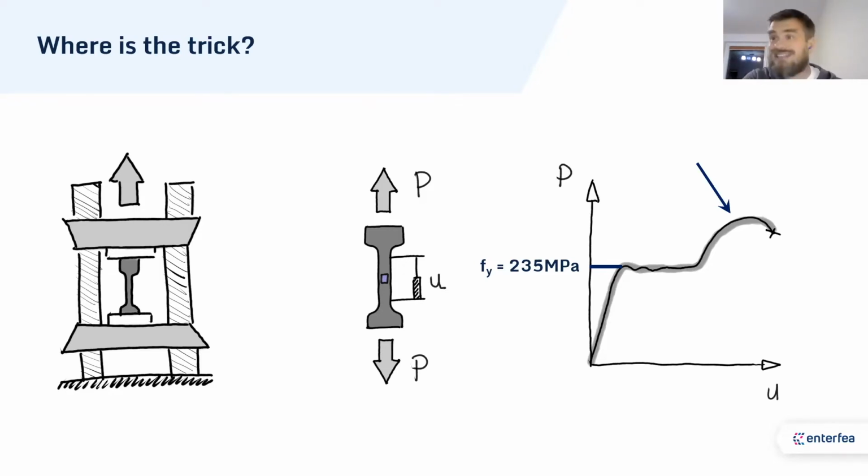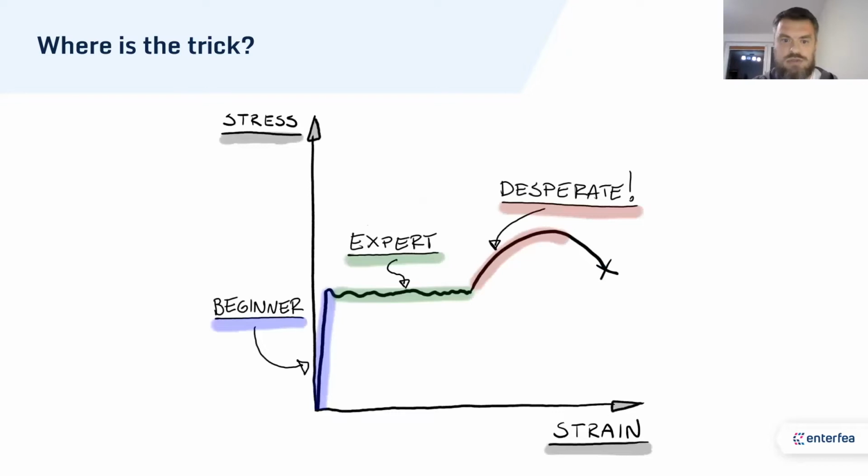So clearly that's the trick, right? This is where the extra strength is in my material. Actually, it's not. It's in the plastic plateau. So firstly, the stress on the top there would be like 360 according to Eurocode. So it's still at least 2 times too little to solve the mystery of why this hasn't failed. And the plastic plateau is something which is very often not understood. And I want to explain this to you as we move on.